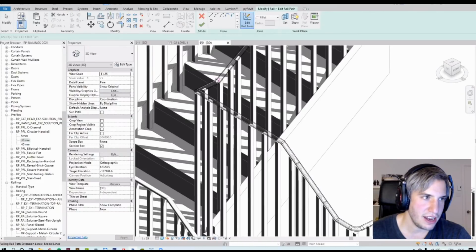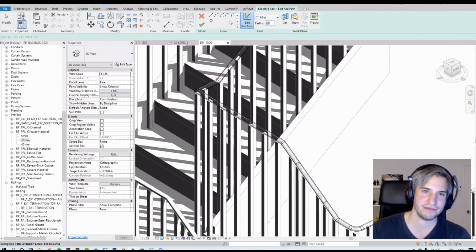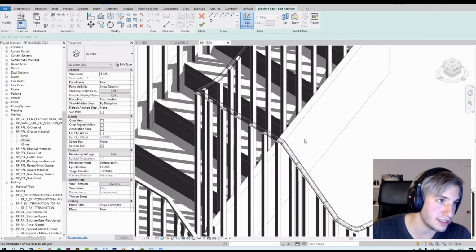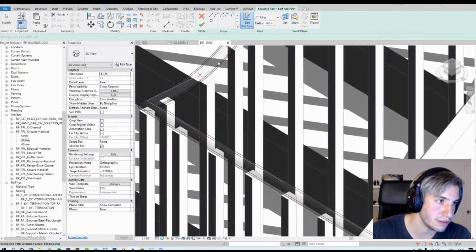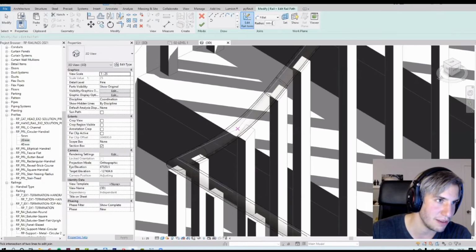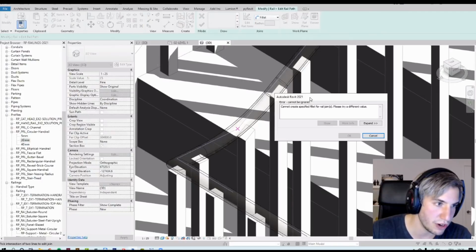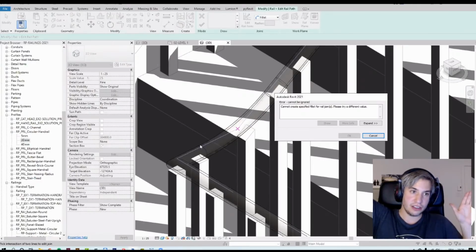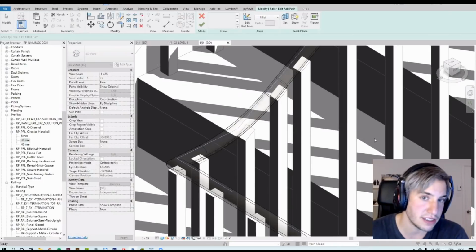I'm going to ask everyone out there on the chat to let us know if you knew about that. I'd love to hear it. Awesome. Something to know about: if there were a big value, like say 300 here, did it work? It did. Okay, I'm going to put something even bigger. Let's say 600. Then I get a warning. Basically the transition would be a radius so big that it would extend over to the next joints. So it caused a conflict, and Revit doesn't like that, so it stops you from doing it.